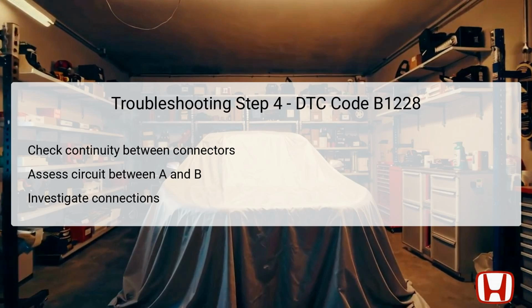This continuity check is crucial in determining if there is an electrical fault in the circuit connecting these two terminals. If there is continuity, it indicates that the wiring between these 2 points is solid and that the signal is likely valid at this stage.